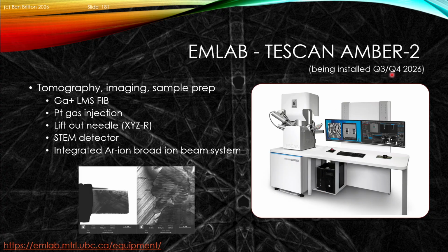And in this instrument, this is set up largely to be sample preparation for TEM and micromechanical testing. So this is a gallium source. It's got a platinum gas injection system. It has an XYZR lift-out needle, a STEM detector, and the integrated argon broad ion beam system. And you've seen that beautiful example of the lamella prep as presented here. More details are located on our facility website.